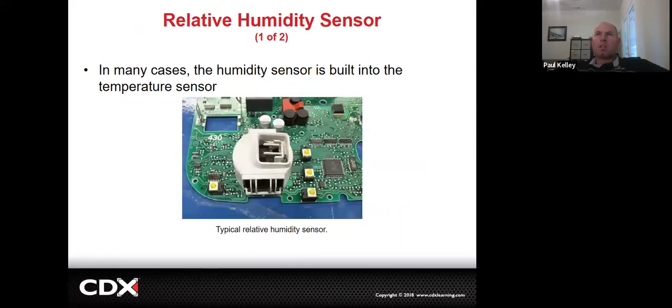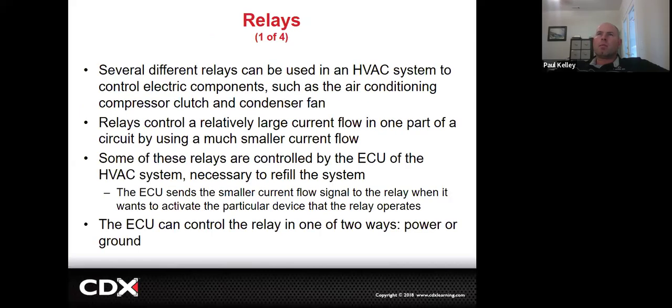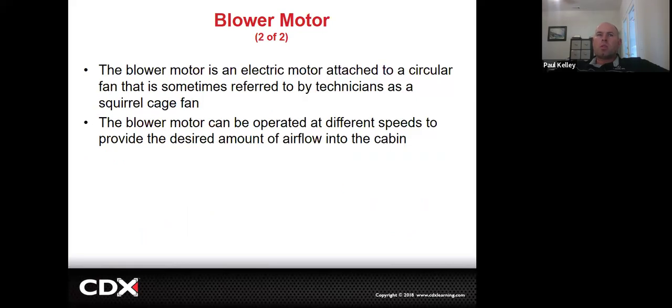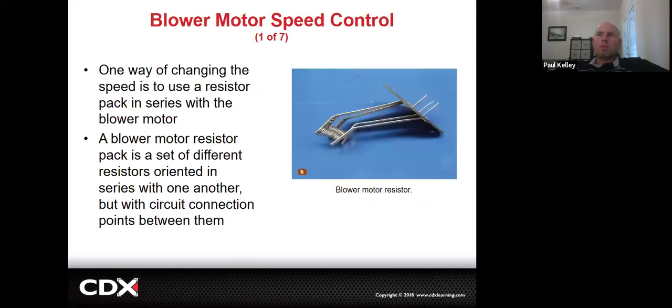Cool. There's a humidity sensor. We don't do a whole lot with that, but it's possible. I think you guys are good on relays. Blower motor. When we talk about the blower motor, we do want to talk about this resistor. We may do a little bit more of this in person, but for now, do you see these resistors? They're like coils. The more it's wound, the longer it is.